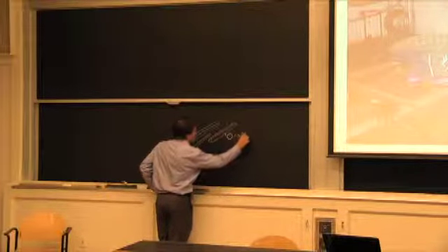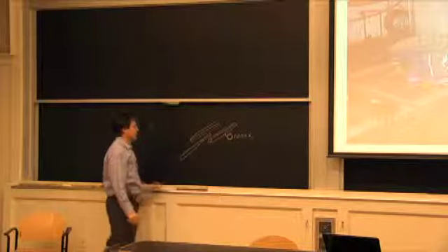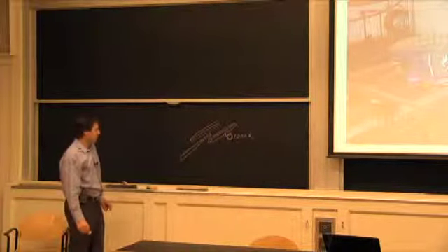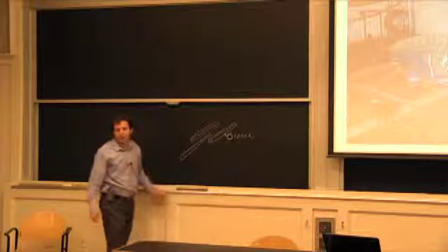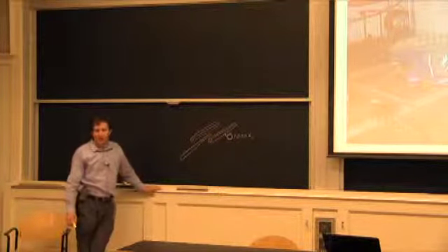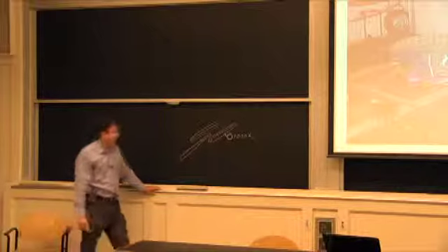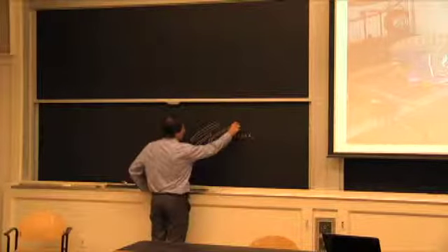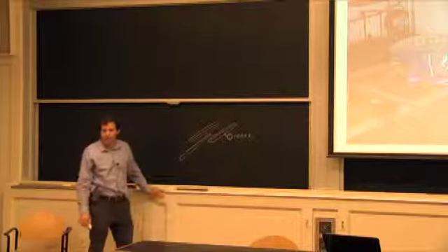So single axle, 1,000 pounds. Are you going to put the whole load on one side of your trailer? Probably not. But that's where, in my case, I said that would be my safety factor. So I'm going to put 1,000 pounds on that beam and make sure it doesn't deform permanently in the middle.